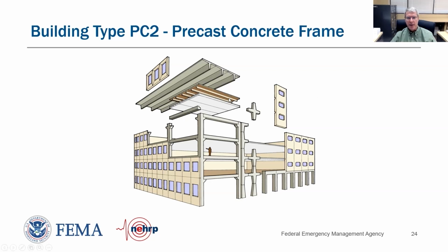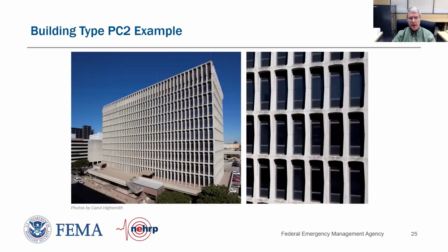Then we've got precast double T's, which is generally pretty common for parking garages. We can also have precast cladding for the exterior cladding system for these buildings, and then the beams and columns are all precast separately and trucked out to the building site. So here's a rather tall precast PC2 building, and if you look in very closely, you can actually see the star joints at the beam column interfaces or connections that were constructed. And then the next level is above that, along with the column.